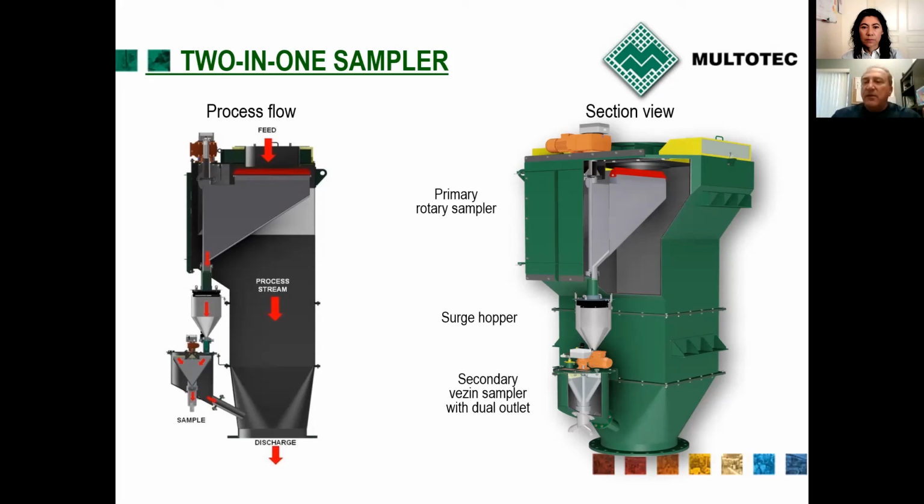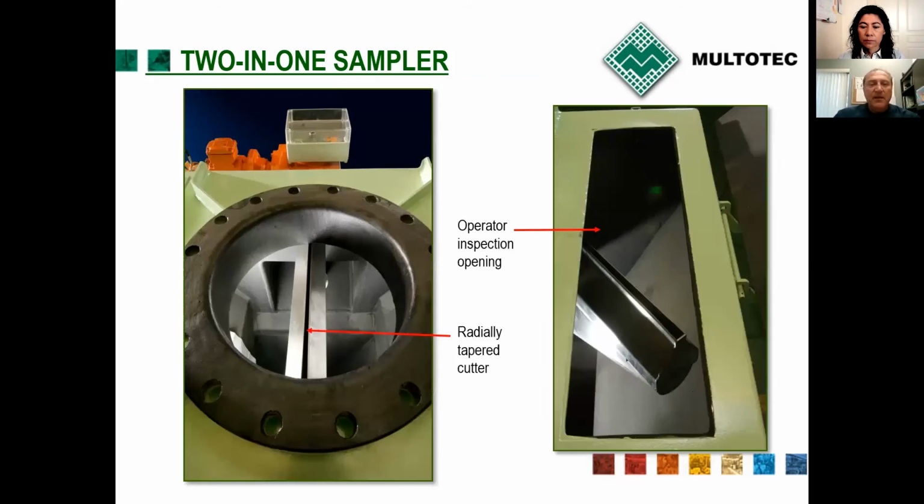Of course, if we collect every 15 minutes, in between the slurry will flow freely between the entrance pipe and the outlet pipe. So this is the inside of a sampler. This is your entrance pipe, and this is the collecting arm from the inside, with the cutter opening, which is sized according to the theory of sampling.